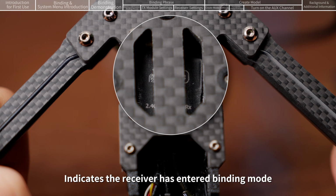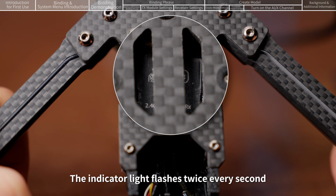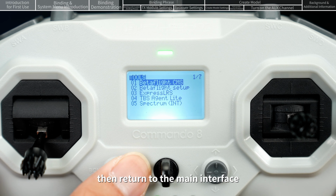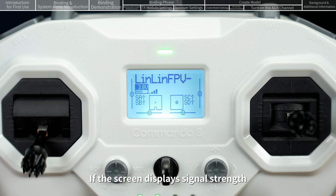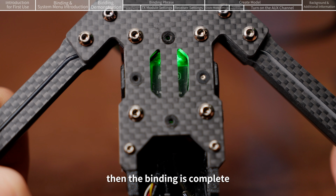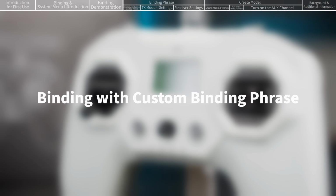Indicates the receiver has entered binding mode. The indicator light flashes twice every second. Press bind on the remote controller, then return to the main interface. If the screen displays signal strength, and the receiver's indicator LED changes from blinking to a solid state, then the binding is complete.